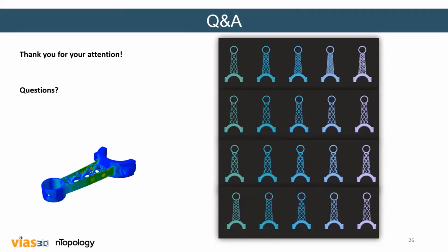The other question is, is it possible to do point impact on a circular design in nTopology? There are simulation techniques within nTop, but they're going to be limited to linear static analysis. So if you need deformation or non-linear analysis or transient, in this case, we can just export a model out to another simulation software. So you can look into that if nTop's native analysis tools aren't able to capture the physics you're trying to do.